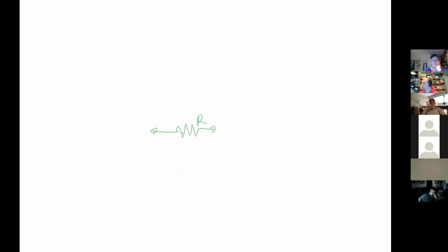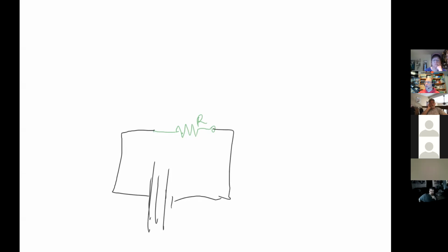And at the very least, let's say that there is a battery in the circuit that goes like this. Somewhere in the circuit, you're going to have to take that battery out in order to keep from getting a bad reading, at the very best, and at the very worst, blowing up your meter.